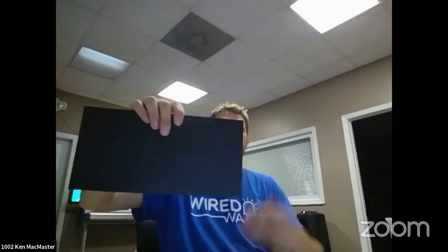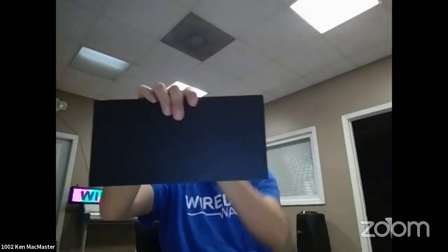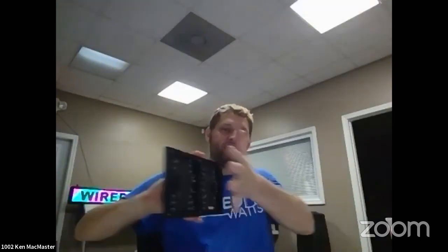Is it not recommended to winterize indoor panels for outdoors? So when it comes to outdoor panels, your outdoor panel is going to be waterproof on this side, this side, this side, this side. It's going to have weep holes in the bottom, and this side's going to have a covering on it, like a little bit of a gel coat, but it's not waterproof. So this side here gets gasketed up against a piece of sheet metal with, I think, 12 or 16 screws, and then there's a rubber gasket that goes all the way around it.